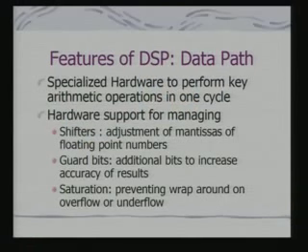And this design comes from the requirements of numeric fidelity. Saturation we have already seen. The saturation instructions are in fact in the DSP extension of the ARM, so that there is no wraparound, and this is important for delivering or managing signals having values within logical limits. Therefore, what I was talking about with relation to the guard bits is that of precision.